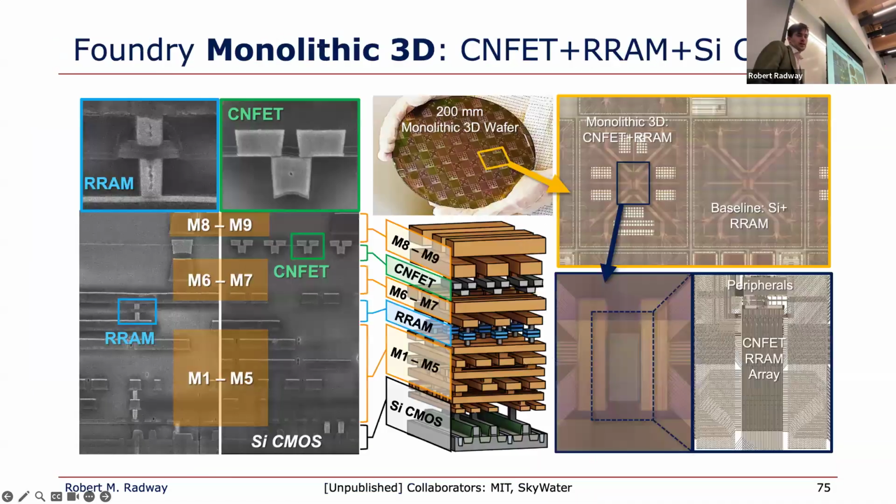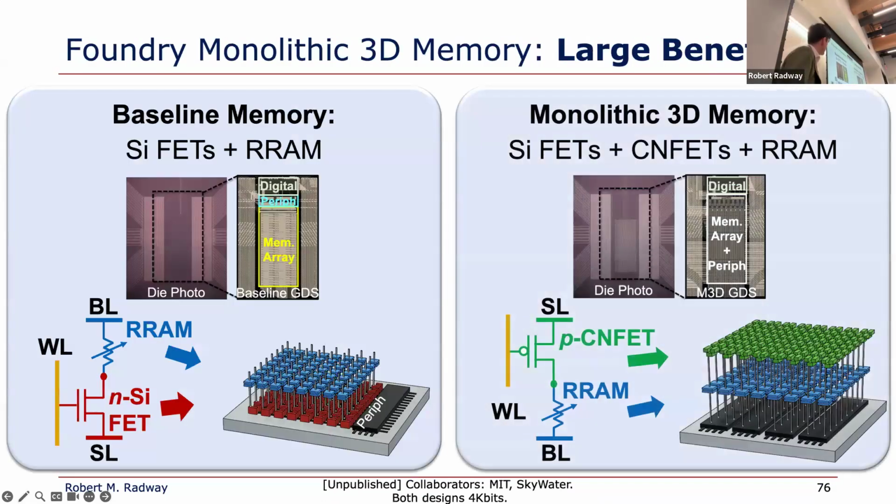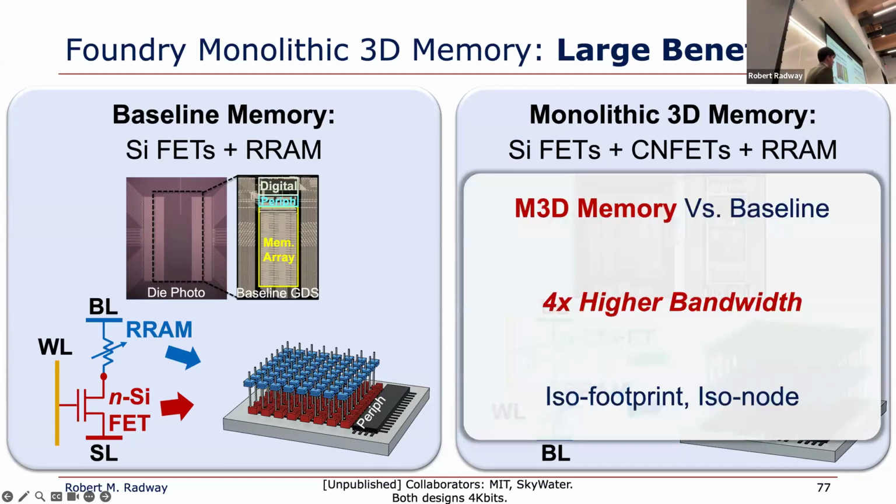And the main reason is that effectively, this is an example of a RAM array. So let's say you have your readout circuits, and then you have your actual storage bit cells. They take up some amount of area in that silicon in a traditional silicon approach. Using new devices, we can move that into those upper tiers, and we free up this front end space. So now we can design new circuits to use that space to give us performance improvements. We can increase our bandwidth.